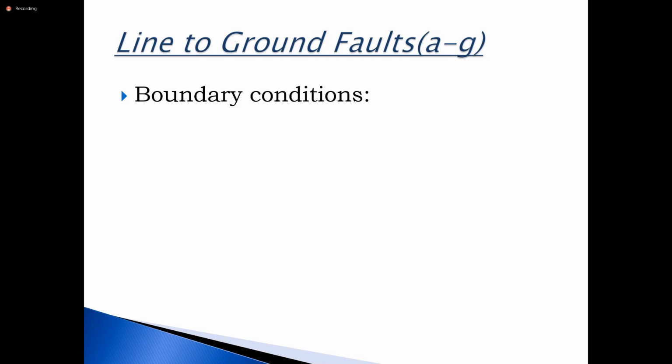All right? So we start out by looking at the first fault type, which is that you have a line coming in contact with the ground. Now that can happen in a myriad of ways. One, the line can come in contact with a tree. So, during heavy wind, or for some reason a limb of the tree is broken, but still attached to the tree.